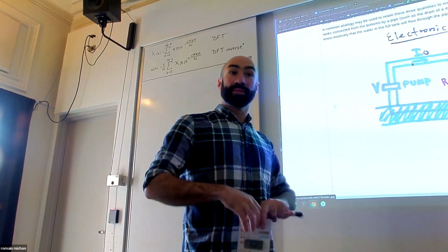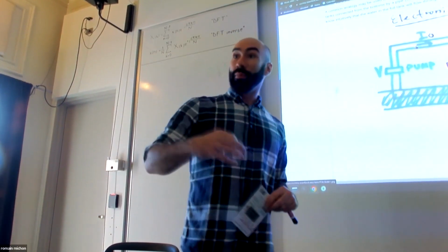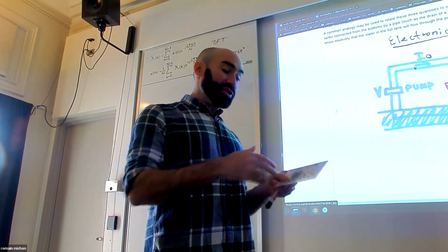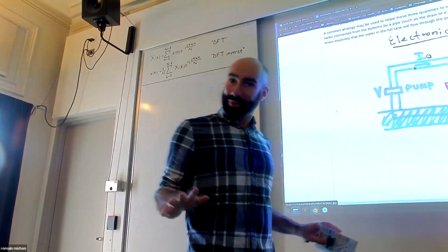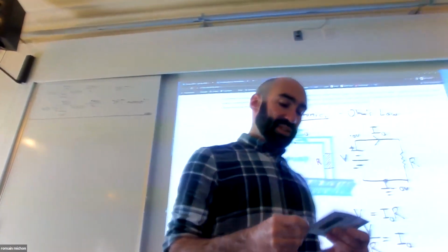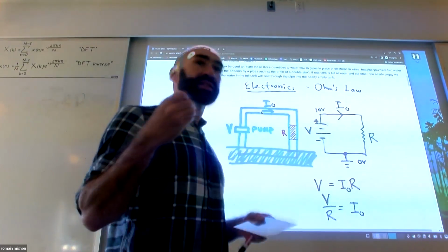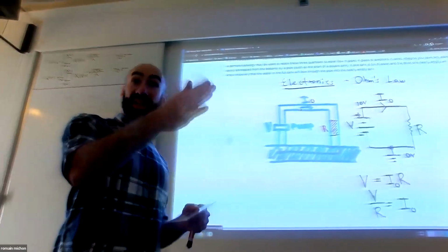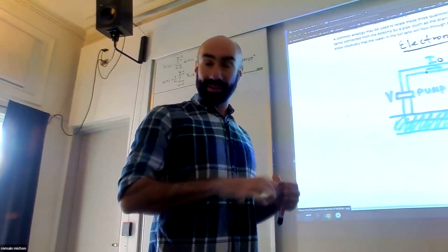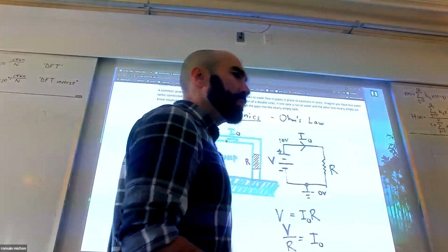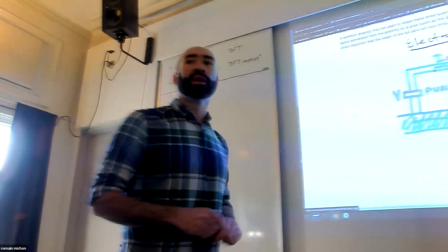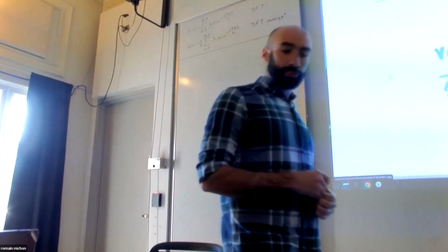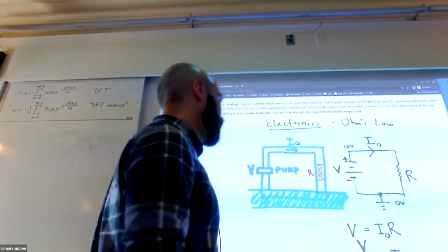If you want to power something big, you need an external power supply. And the external power supply is not going to send energy through the Teensy, because otherwise it would completely destroy it. So it means that in many cases, you're going to need an external power supply that brings power to the system outside of the Teensy, not going through the Teensy. We'll talk more about this, and I'm sure that some of you for your final projects might actually need that, but some of you probably won't.